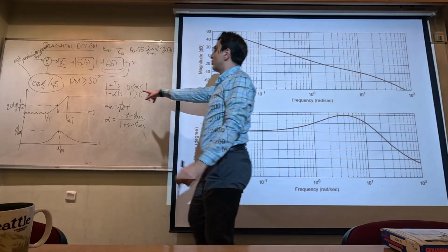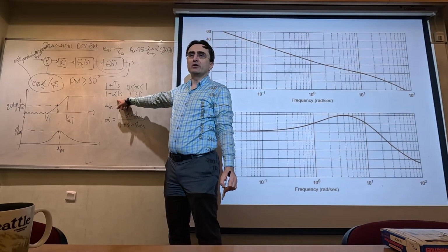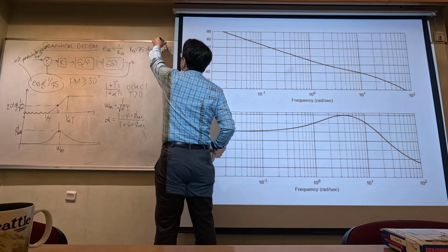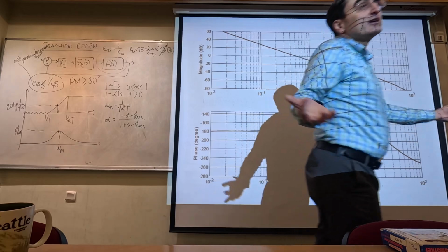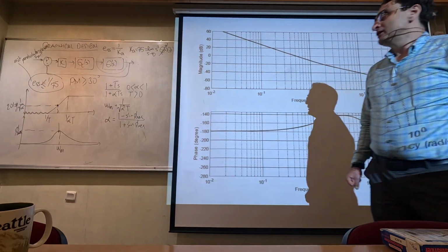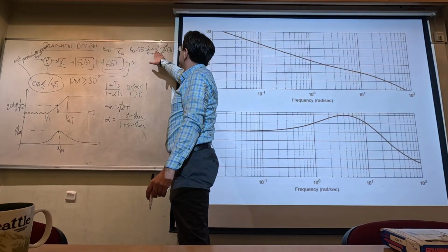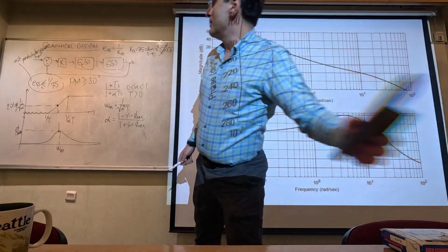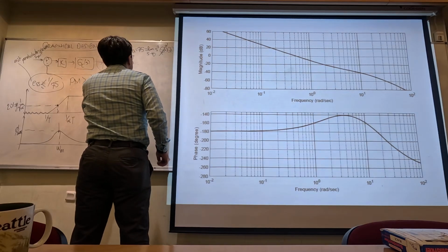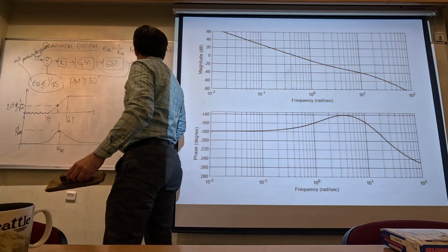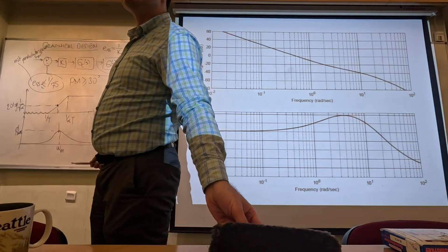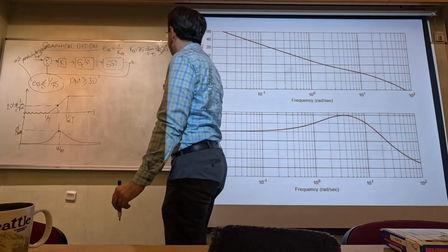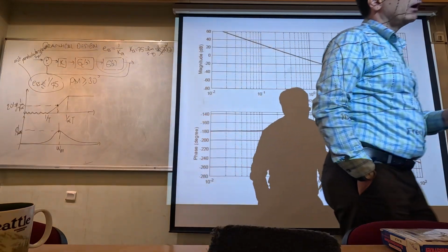And when you let s go to 0 in this compensator, we see that this becomes 1. That means that the compensator really does not contribute anything to the steady state error. And that actually means that I can only consider this s squared term and G of s term. And now we can try to find what k should be. I have forgotten something here. What is that? I have forgotten k. Obviously, this is the open loop transfer function, so I need to put k there.